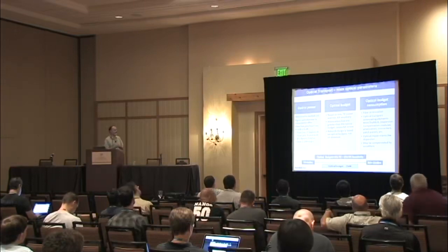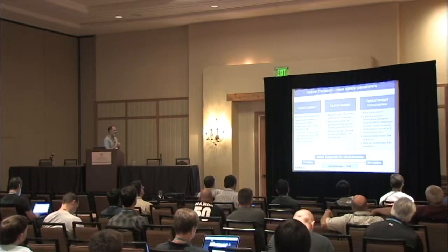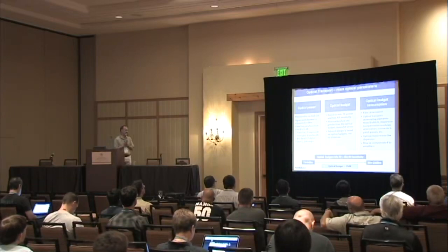It's based on minimum transmit power and minimum receive sensitivity. So looking at the example, we have a transmitter of 0 dBm, a receiver of minus 23 dBm. We have an optical budget of 23 dB.